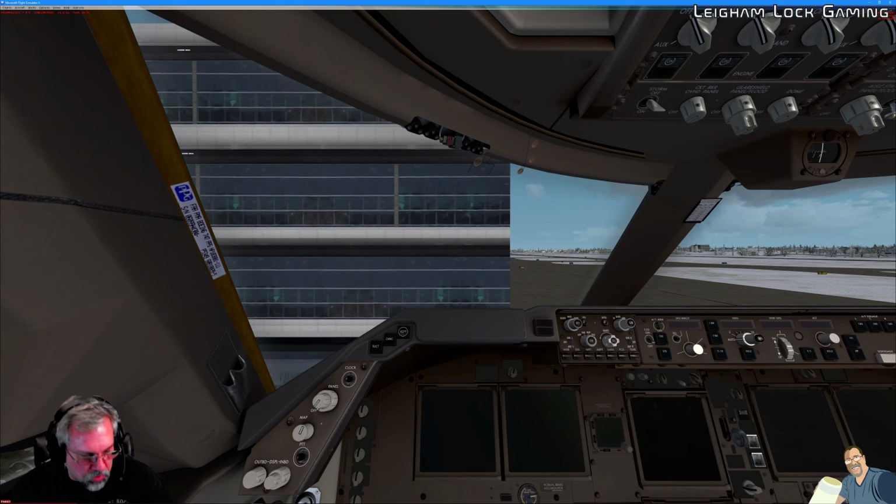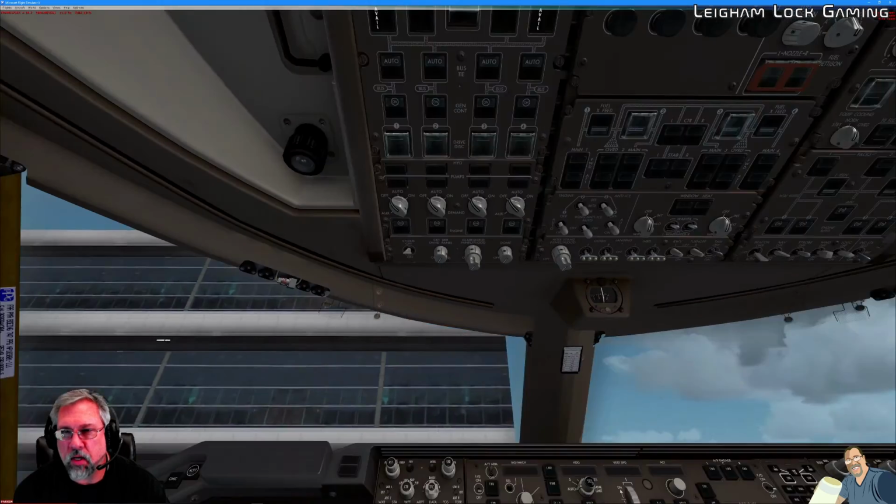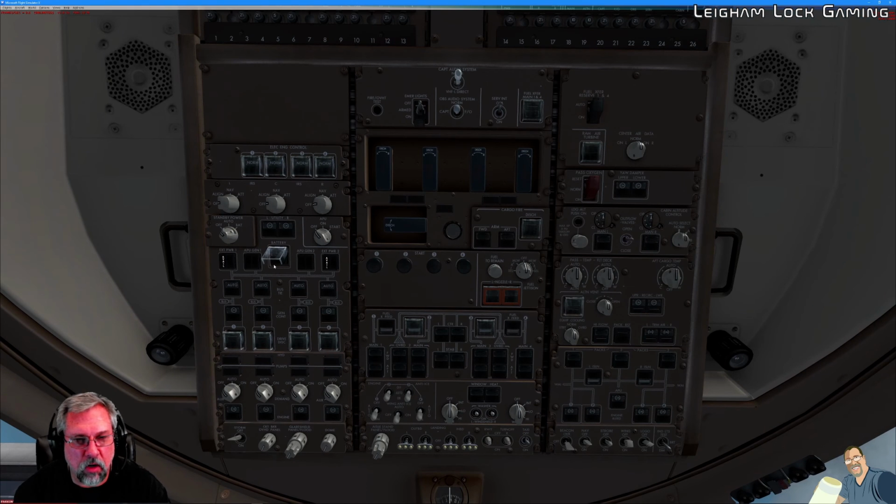We know we've got external power and air conditioning attached, and we're going to start working through our checklist. We already have the jetway connected. We've confirmed those settings: wheel chocks, air conditioning, power connection. So we want to go right to the overhead console and get our battery turned on. And we'll see that parts of the aircraft start their initialization. We can also see from the instrument panel in the overhead that the external power is connected. We have the avail lights on external power 1 and external power 2.